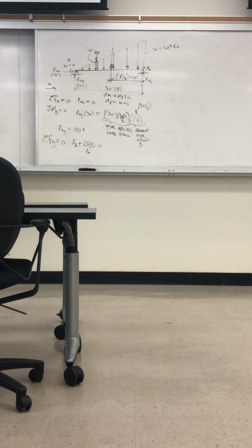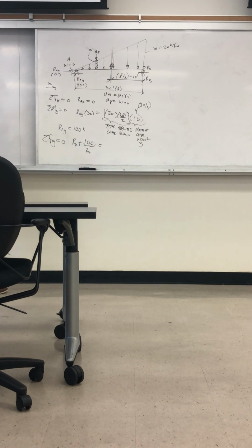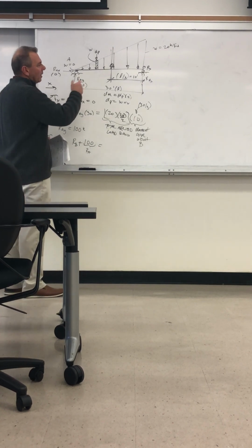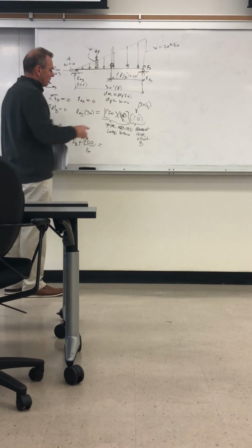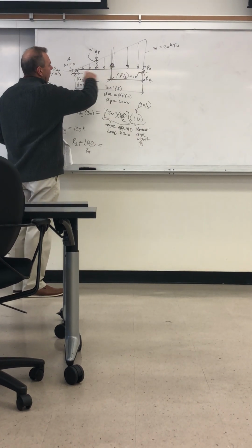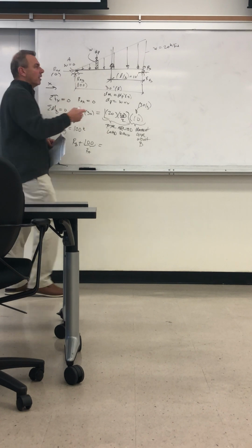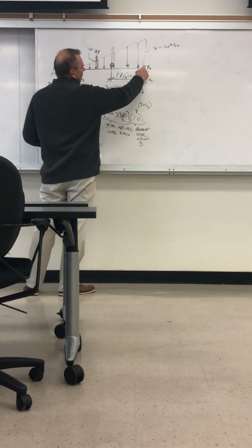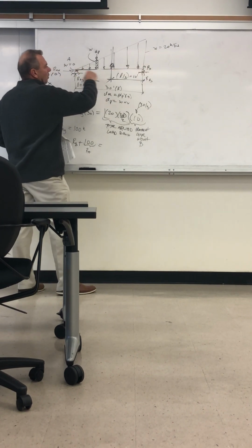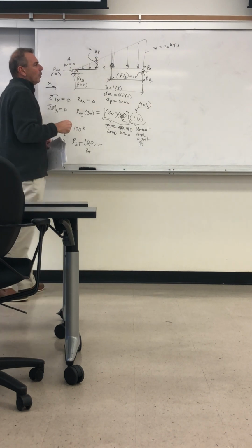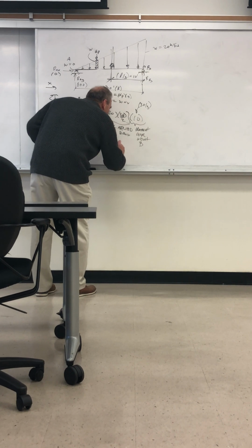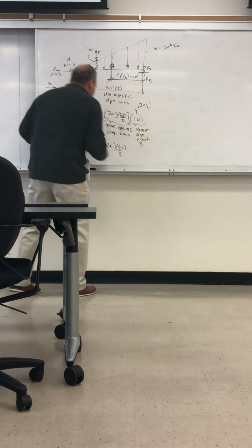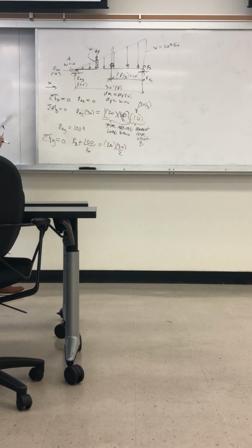Okay, so R sub B plus 100 equals the weight down. Now again, we'll just use the total area to get the total weight, just like we did here. So that's 20. It's just the area of a triangle, right? Area of a rectangle would be the height times the width, and that would be doubled, and we want 1/2 of that. So that's why it's just 20 multiplied by 30 over 2. Then we can solve for reaction.